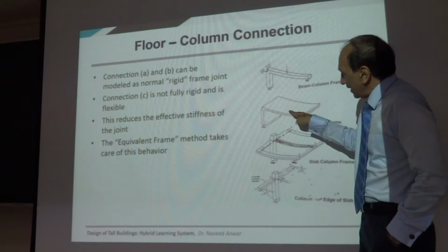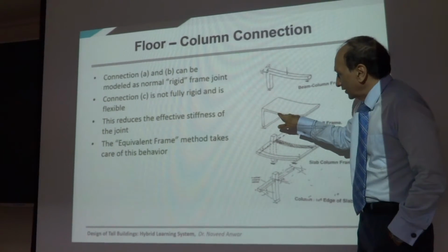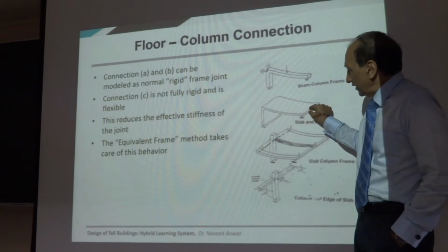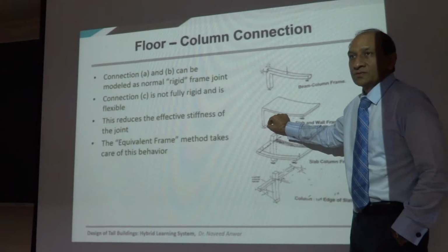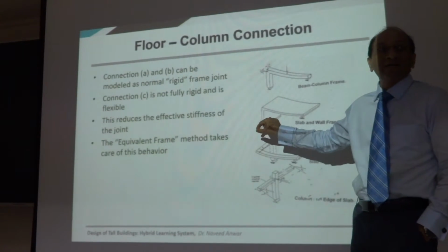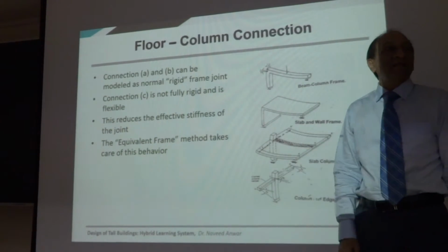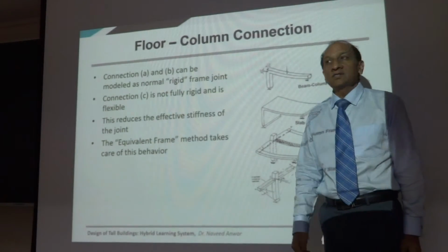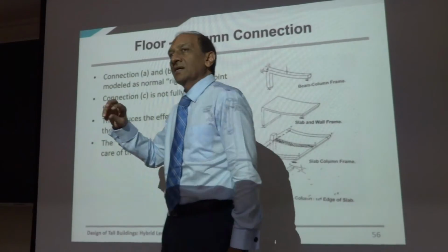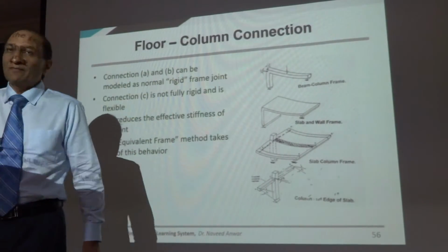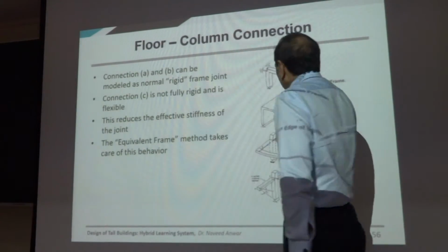If you have a slab and the same width of wall, same thing, it doesn't matter, because each strip on the slab and column are the same, so we can divide it into small strips and analyze them as frames, because the deformation compatibility is 100%, identical at every location along the way.